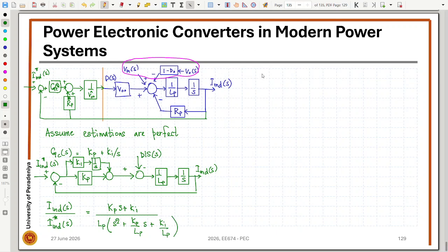If we take the switching frequency as 16 kilohertz, let's assume that our controller bandwidth will be 8 kilohertz, and I will take the pole location 1 as fc divided by 10 and fp2 as fp1 divided by 4.